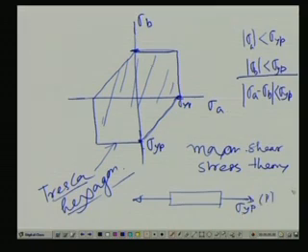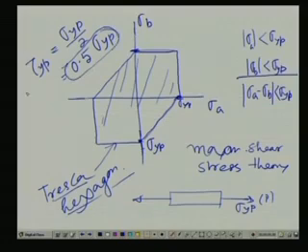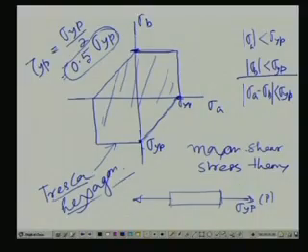By this theory, what is predicted is that tau yield point should be sigma yield point by 2, that is equal to 0.5 sigma yield point. It is not exact, but it is quite close to the experiment. Well, we have other theories which we can continue in the next class. Thank you.